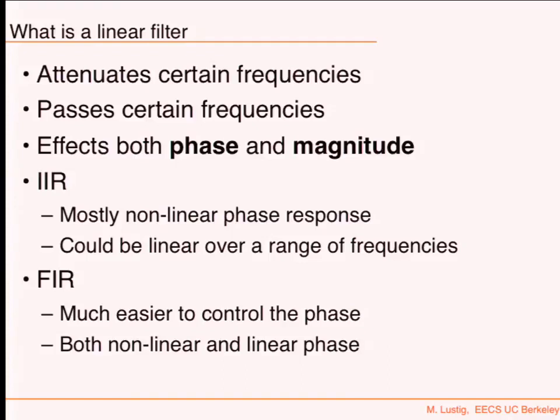But obviously, the result will not necessarily have a finite impulse response. So what I will need to do is approximate. I'm going to approximate my desired impulse response through a finite set of filter taps that we will convolve our signal with. That's the whole idea about finite impulse response.